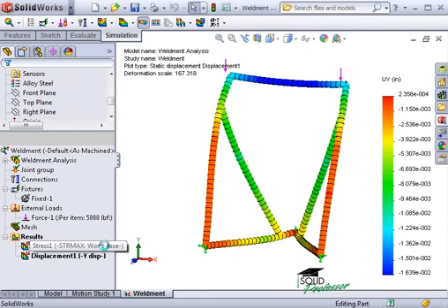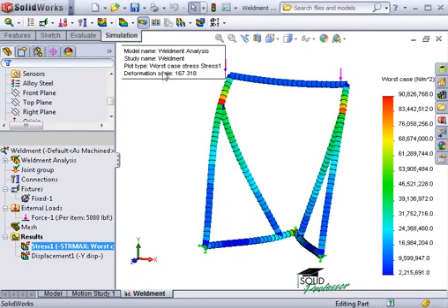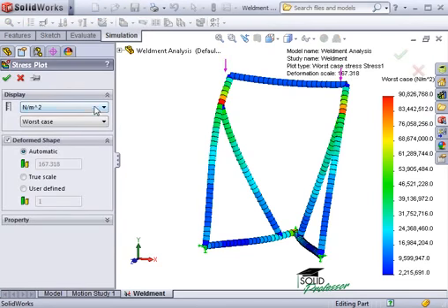By default, the plot is displaying the worst-case stress. Worst case combines axial and bending stresses. Again, I'll double-click the plot information to bring up the plot options. Notice I can plot axial and bending stresses individually. Bending stress will differ depending on the direction you're considering. In our case, we're working with rectangular tubing, so bending stress will be different in the longer direction of the rectangle as opposed to the shorter direction.